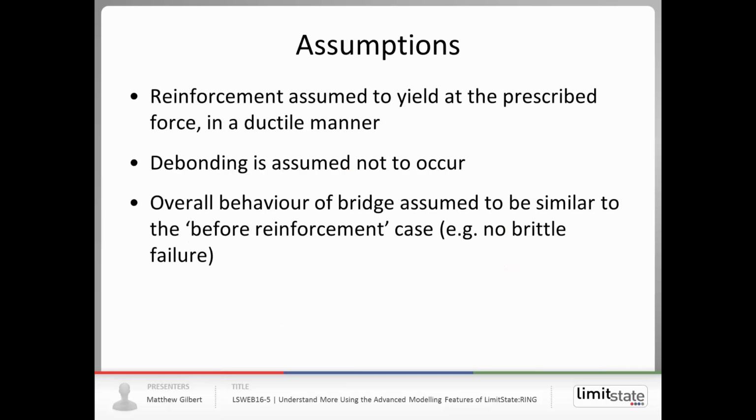Key to note, there are some assumptions. So you assume that the reinforcement yields at a prescribed force in a ductile manner, and it's assumed that you don't get debonding of the reinforcement, and perhaps most importantly, we're assuming that you get a similar global response before and after reinforcement. So it's only really suitable if you have relatively light reinforcement where you're not expecting to get a completely different mode of response and potentially a brittle response.